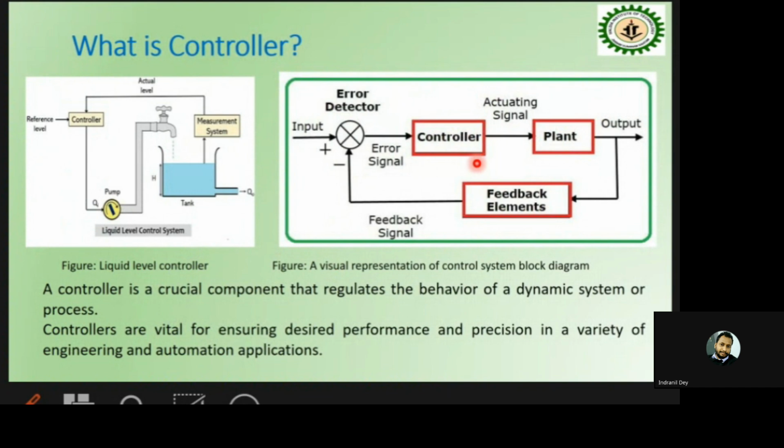but among those you should select one or multiple parameters to control. Then those parameters will be our control variables. So now we have the feedback path here. In this feedback path, we are supposed to use some instruments, some sensors, which usually measure the process variable, which is acting as a control variable. Those will measure the data of the plant output and give it back to the comparator.